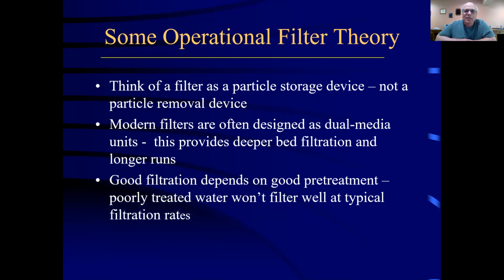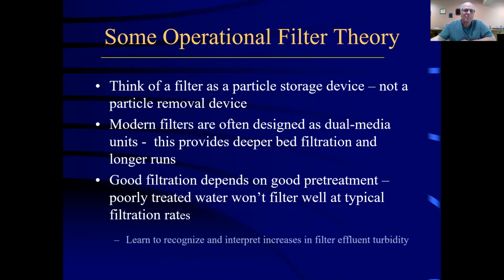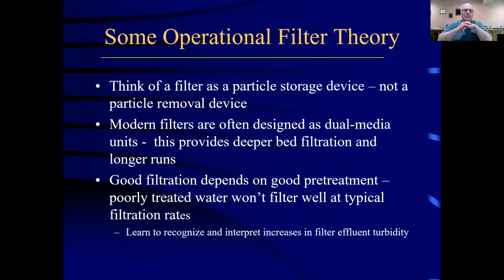So good filtration then is going to, of course, depend on good pretreatment. If we don't do a good job in flocculation and coagulation, we're going to have poorly treated water. We're not going to filter that water very well. The best filters in the world, the best designed and maintained filters in the world, won't filter poorly pre-treated water.